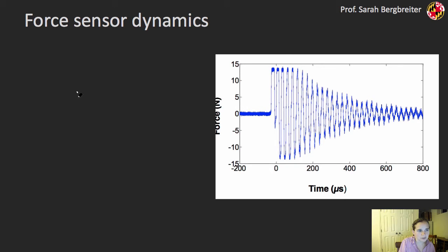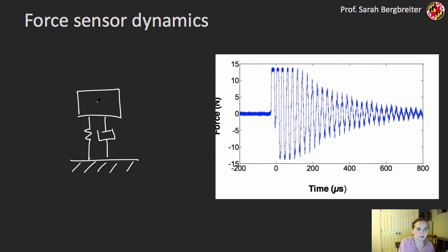And this is because if I were to crack open that force sensor and look at what is inside of it, I could effectively model that system by a basic mass spring damper. So I have a mass, I have a spring, I have some damping here as well. And so what I'm probably trying to measure here is this distance between the mass, for example, and the ground. And as that deflects based on some applied mass to it, I'll be able to see that change in displacement.